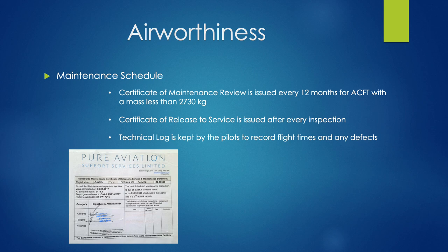The technical log, and every aircraft has one, which records all the times of flying and any defects, is kept inside the aircraft or it could be on a digital form, so a spreadsheet, but it needs to be readily available so we can record the times of flight, how often, and then by recording the times of flight, we know how often or how soon we need to do any maintenance scheduling, and if we see any defects on the aircraft, so any issues, that can also be reported in the technical log as well.